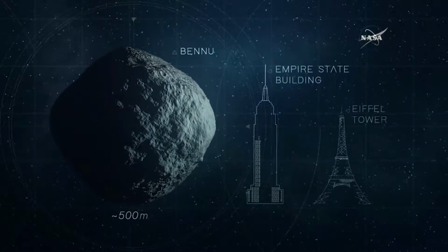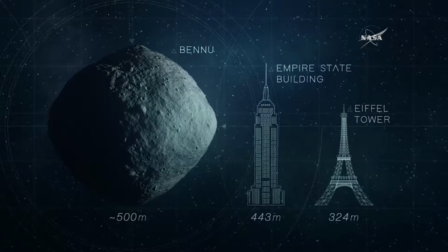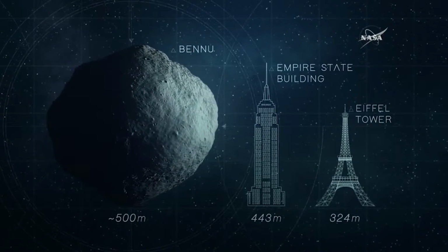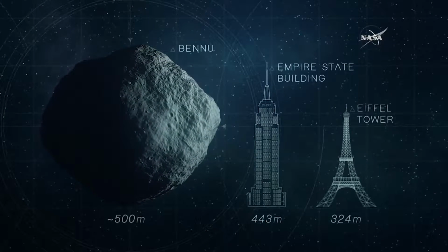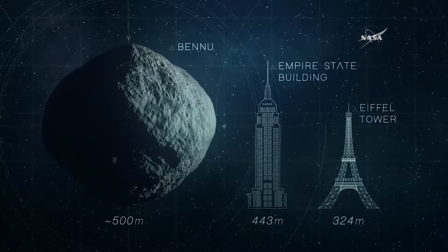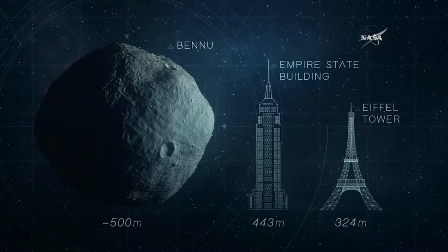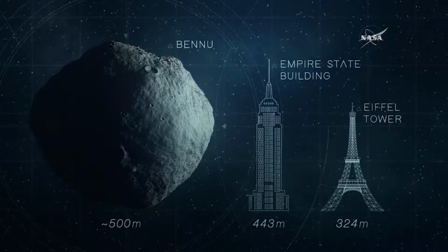The next criteria for selection was finding an asteroid that was the right size to enable two critical portions of the mission: the proximity operations close to the asteroid and the actual collection of the sample. And go ahead and start my next graphic. Asteroids with small diameters rotate more rapidly than those with large diameters. For an asteroid that has a smaller diameter than 200 meters, it can rotate rapidly enough that some of the material on the surface will be ejected. Furthermore, it's difficult to match the rotation speed of a rapidly rotating object. So we need an object that's at least 200 meters in diameter.